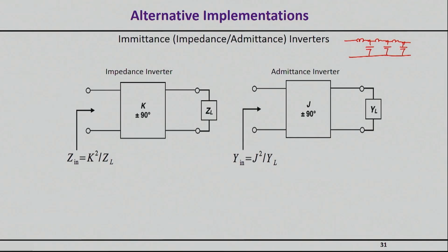in real life. In fact, it turns out, and this is something we'll understand more and more as we talk about bandpass or bandstop filters, that I like to have only a single element to work with, either series or shunt, but not both. And the reason for that is because when I basically work on implementing these elements, for a bandpass or a bandstop, I'm not going to have simple inductors and capacitors. I will actually end up having resonators. And when I have resonators, it's actually a very difficult thing to implement a high-quality resonator. It's a big deal. It takes a lot of time.